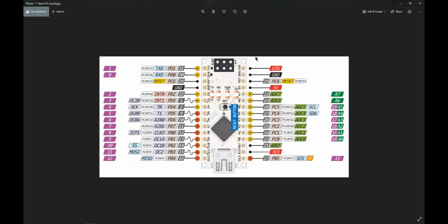As I mentioned earlier, for this specific program for the LED matrix, you can use any pins technically to drive the driver board. However, the Nano has some pins that are specifically meant for certain things. For example, it has what's known as SPI, which is the serial peripheral interface. That is more hardware-oriented pins. Instead of going through software and having a higher level to lower level connection, it's more lower level, so it's a faster connection, more reliable. The pins that we use with this program are pins 10, 11, and 13.